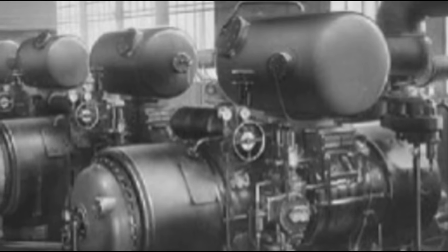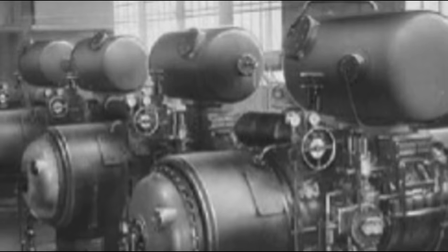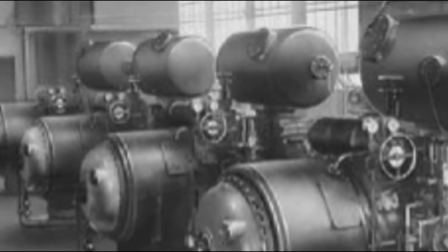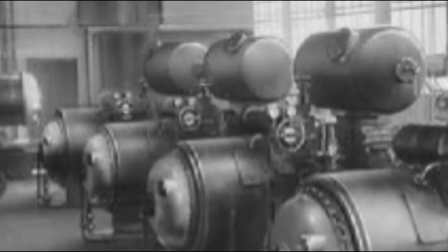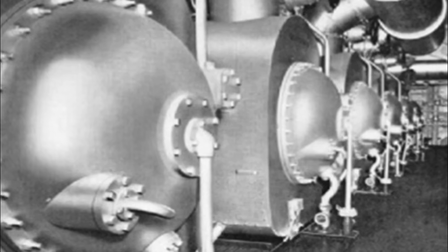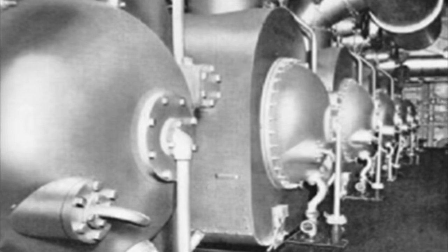A number of factors influence the piston stroke length and the piston cycle rate, which alters the compression ratio and, ultimately, the engine's power. Therefore, active control of the piston stroke during engine operation is necessary. This is accomplished primarily by regulating the fuel supply. Piston stroke also depends on the air pressure in the return buffers.